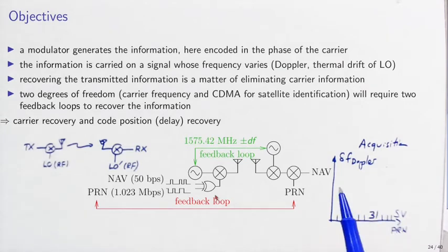And then the second question we will try to answer is how many Doppler shifts will need to be addressed so that we can find the solution, which satellite is transmitting, which will be detected as a correlation peak. So each one of these correlations, trying to find the pseudo-random sequence in a Doppler shifted signal that was received, means we need to make a correlation, and correlation is 3 Fourier transforms. So we see that this operation will be extremely computationally intensive because of all the correlations that need to be processed.